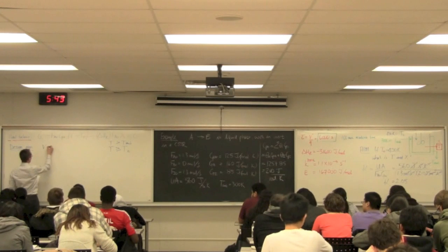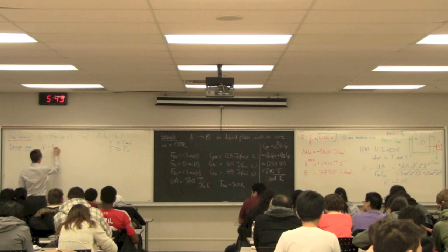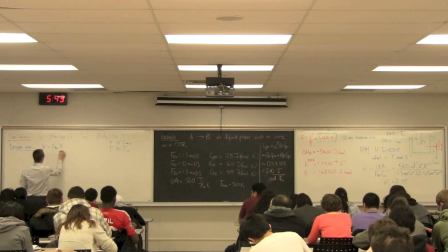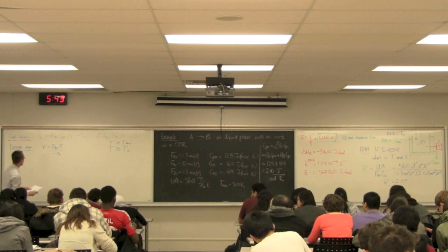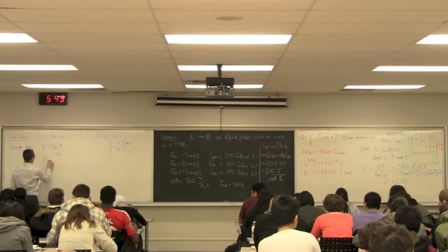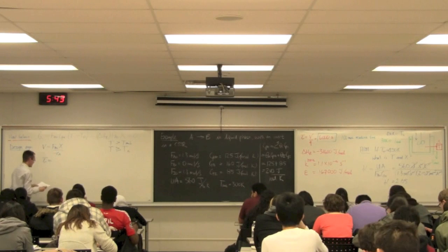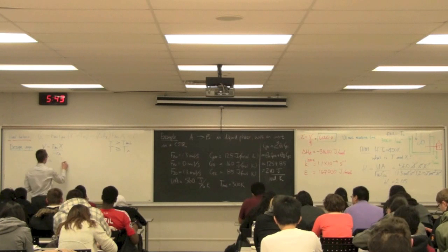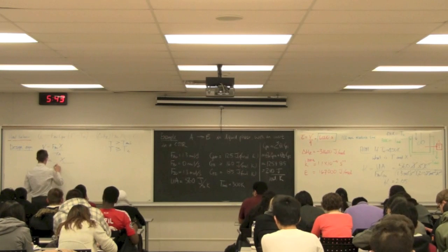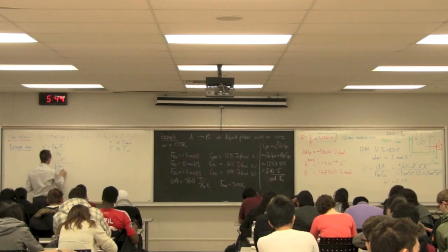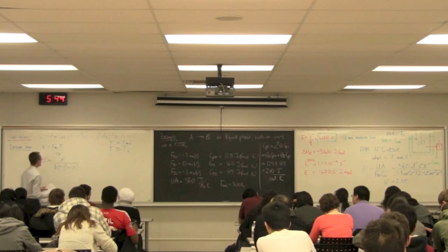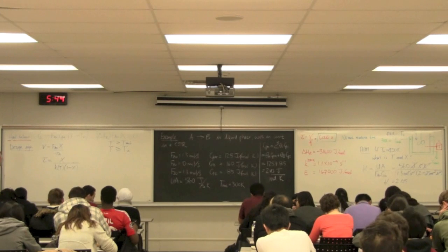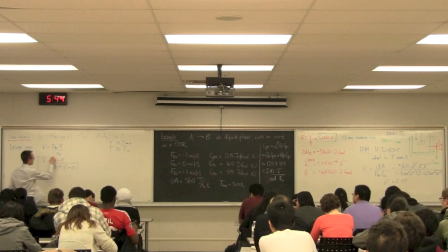Our design equation is the volume of the reactor, F_A0 times X over minus r_A. And we made some substitutions in there last night that allowed us to get to a point where we said the residence time of the reactor is equal to the conversion X over k, the rate constant, which is a function of temperature, times 1 minus X. So there's actually our second equation.